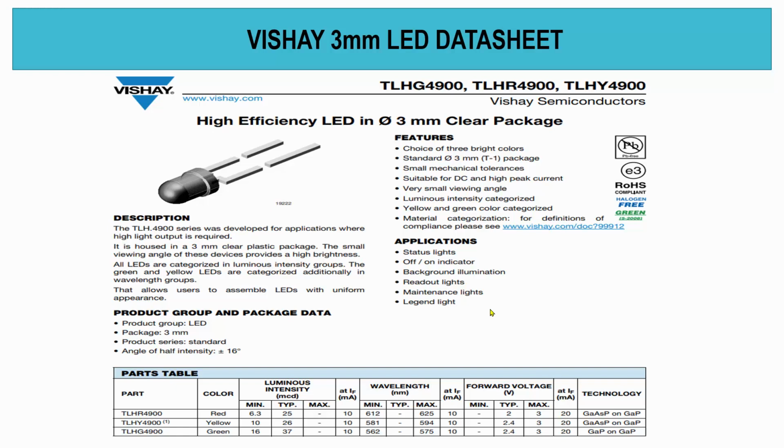It is a status light or an indicator of a circuit turning on or off. So those are a few applications. And the amount of current that they spec here is around 10 mA, or in this case they tested it up to 20 mA. And the voltage they measure is 2V, 2.4V, and 2.4V. Once again, the forward drop depends on what type of color you're using.